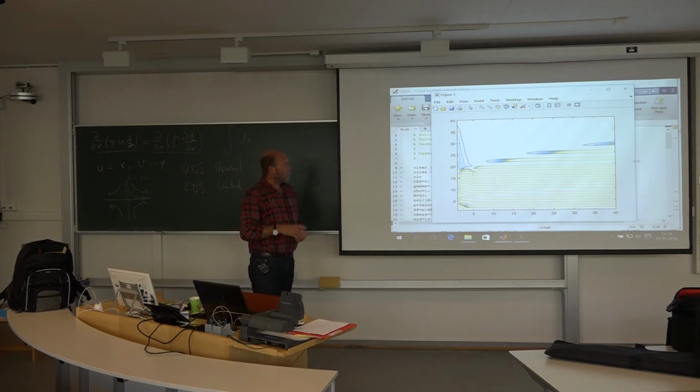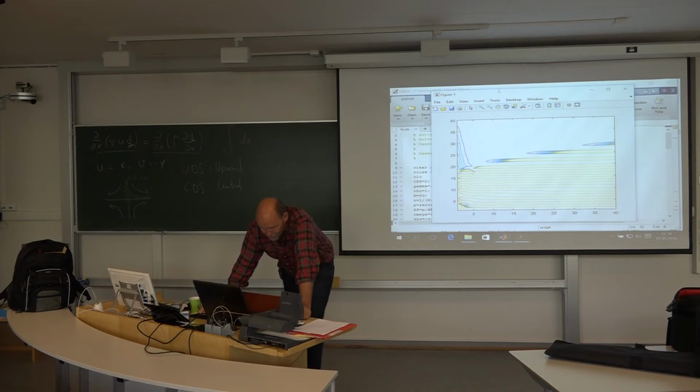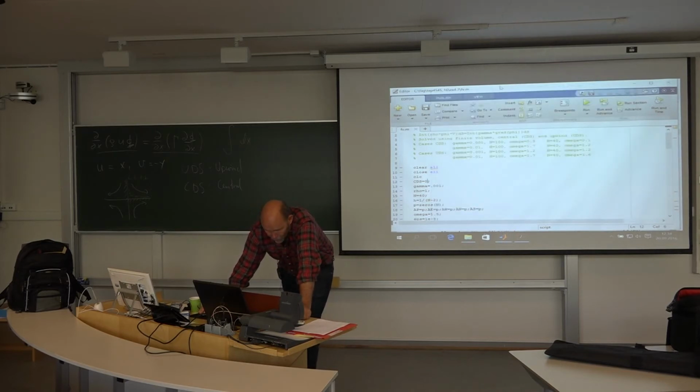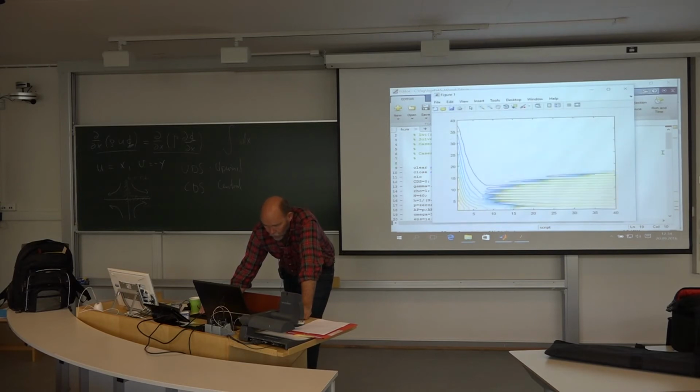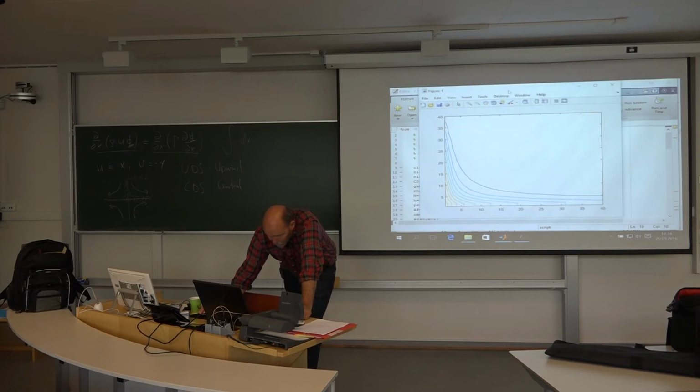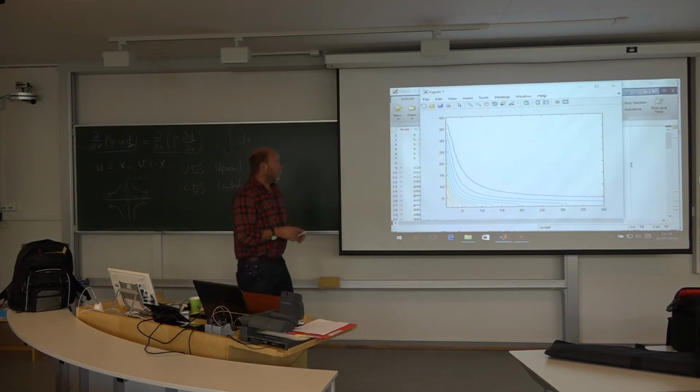And it crashes. So an omega here, over-relaxation, is more than just solving an iterative scheme. It's actually also something to do with stability, obviously. So to solve it here, I actually need quite a small one. I think 1.3 may be okay. Yeah, it survived.